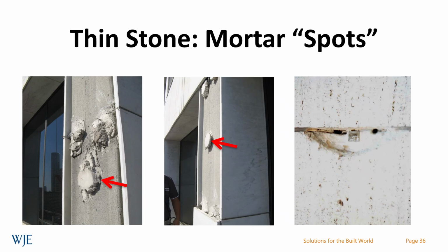The left shows two examples of mortar blobs used in the system, and the right actually shows one of the problems with these, which is that often gypsum was added to the mortar to enable it to set up faster, but as that gets wet over time, it is expansive, much like corrosion scale, and can result in fracturing of the stone.